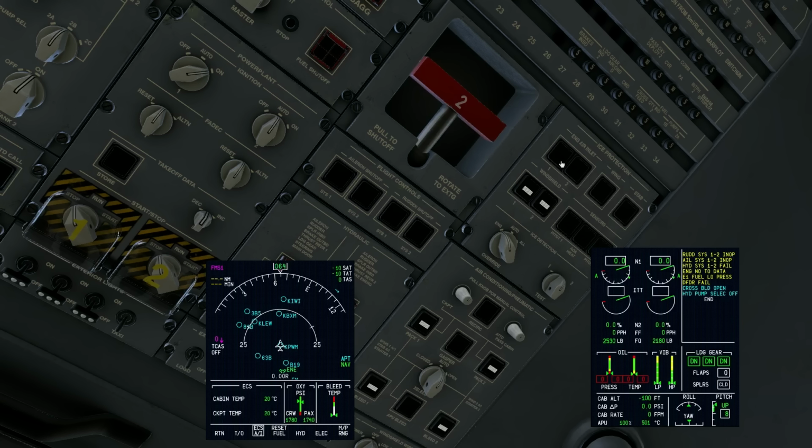In engine, you'll always have the engine, but you won't necessarily get these two unless they trigger. So think of it as auto, it'll only go if it triggers. Engine, get the engine, and these if it triggers. And all, above 25 knots, you'll get everything, no matter what's going on. So this is how, like I said, we interact with the anti-ice system. So it's a very important knob.